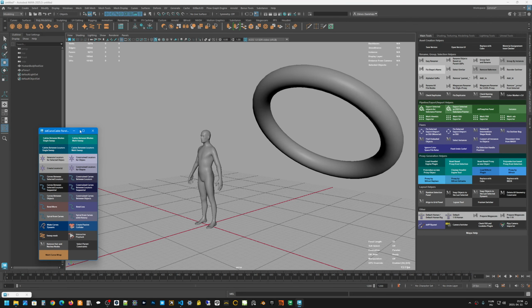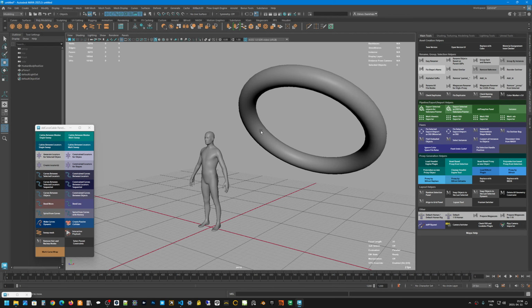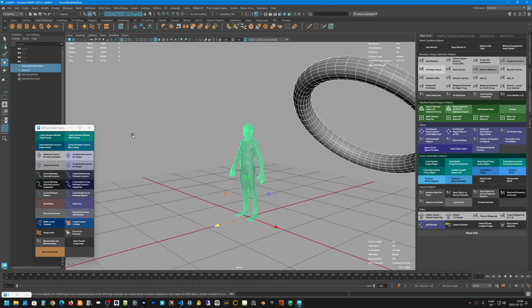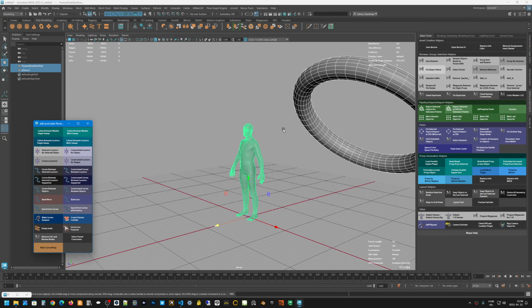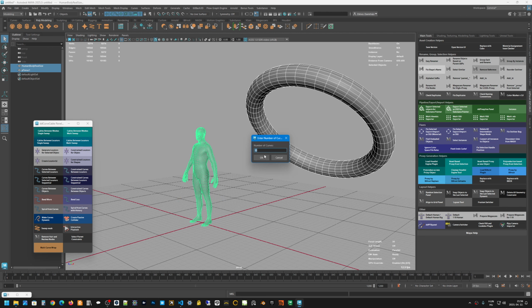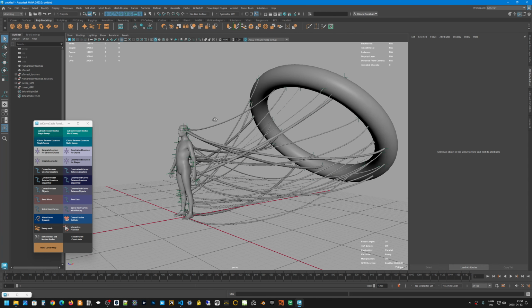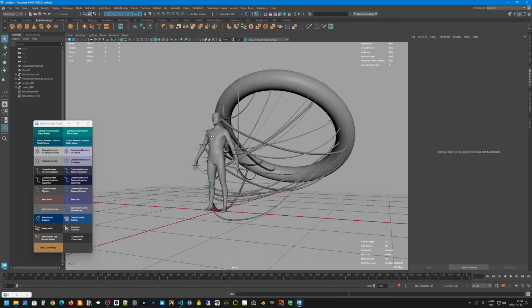Okay, so now a quick presentation of how you can actually use this panel. It's really straightforward, so just select two objects. The main script is created for two objects. Press maybe the cables between meshes multi-sweep. Set the number of curves, maybe 30. Gravity, randomization of the gravity. I just use the default values and that's it.